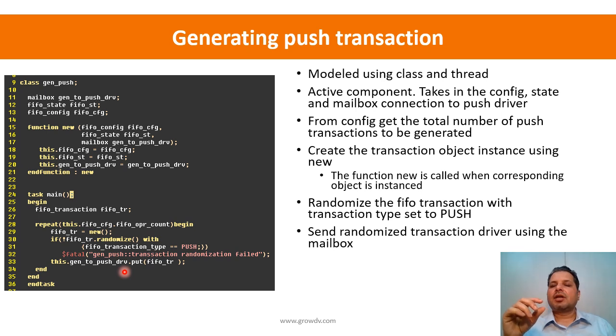Now that is possible only if the functionalities are cleanly segregated, right? And in complex projects, as well as in a case where you are developing a SOC type of chip where you have multiple IPs, there is a lot of reuse possible, and that reuse is only possible if we are cleanly cutting out the components, and one component does one type of functionality: the generator only generates, the driver drives. So when we define this type of clean functional boundaries, then the reusability becomes better, they are easy to maintain, and the debuggability improves. So this is the reason why we divide the functionality into different components.